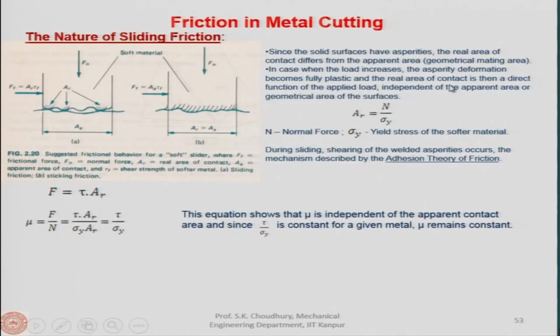Next, the second bullet says that when the 2 surfaces are resting on the asperities and a force is applied to the contact surface, these asperities are initially deformed elastically, and then gradually as the force increases further, this deformation becomes plastic.